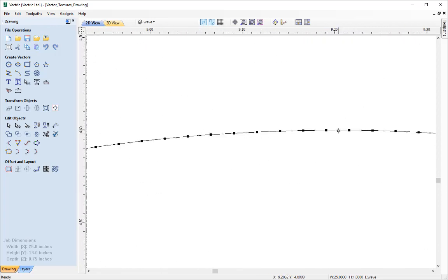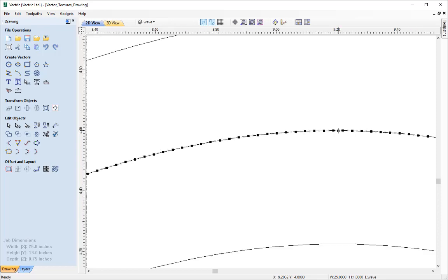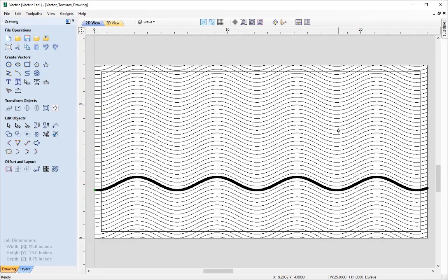Now this won't be a problem for machining, as any curves that normally come out like this in the software will usually be broken up into thousands of tiny little line segments in the actual toolpath code itself. So we won't see any difference in quality from machining these as they are, but in case you wanted to make these easier for editing, what we can do is transform these into Bezier curves to make them a lot easier to edit manually ourselves.